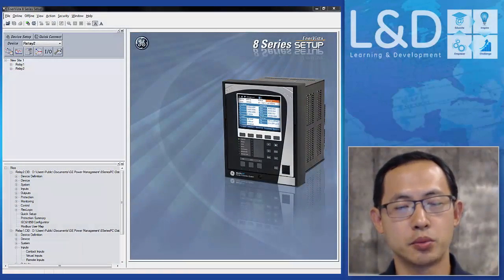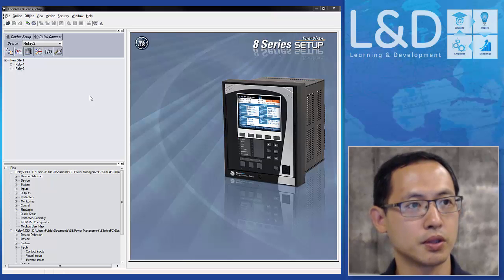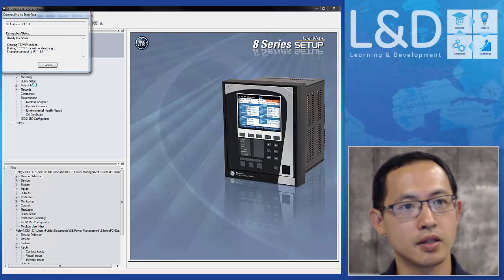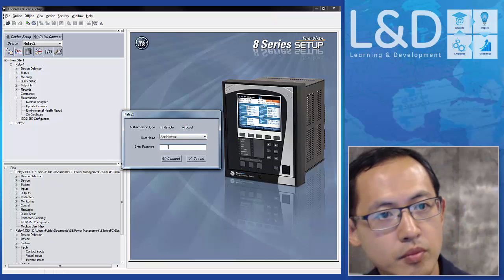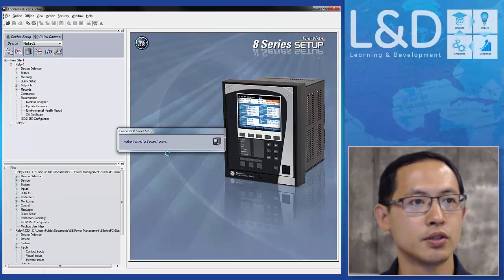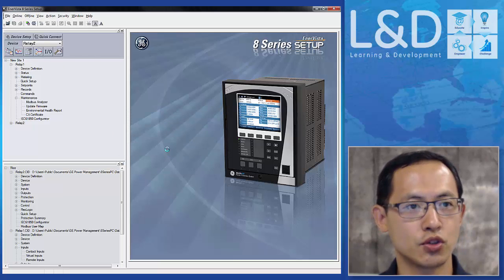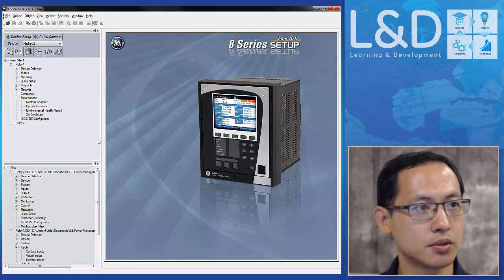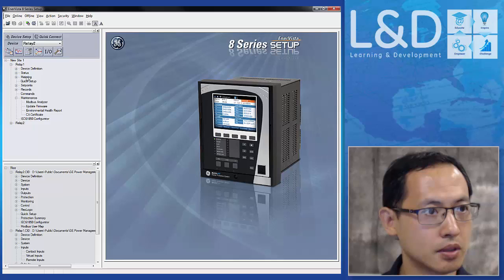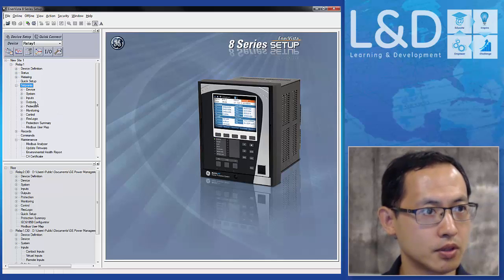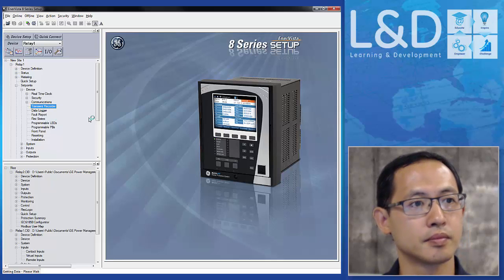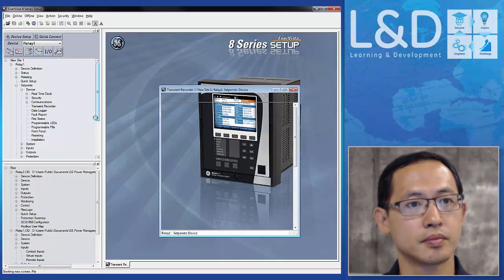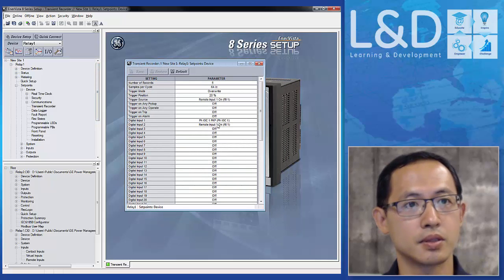Now the relay rebooting is done, so I'm going to do the GOOSE message testing. And before that, I want to set up the oscillography for the relay 1, so I can see the GOOSE message echo back from the originator. So I'm going to turn on the setup of the transient recorder under devices. Okay, so actually this is already preset up.